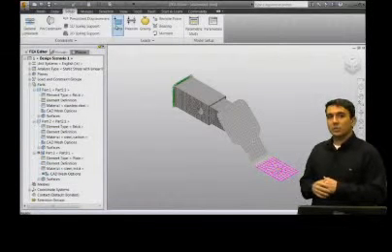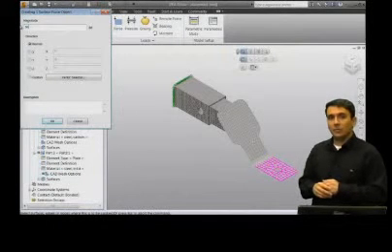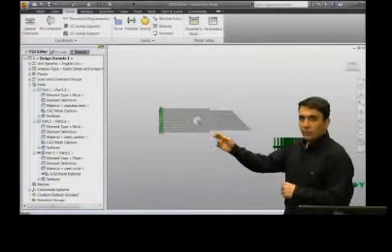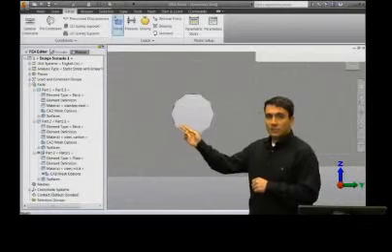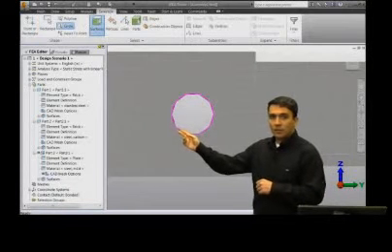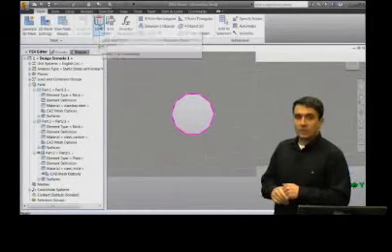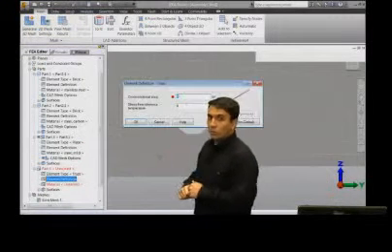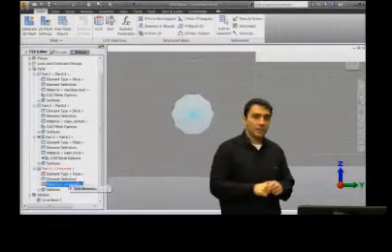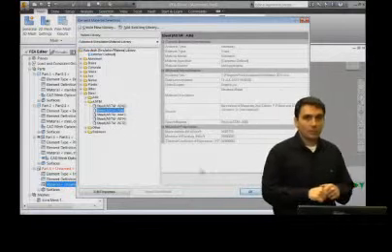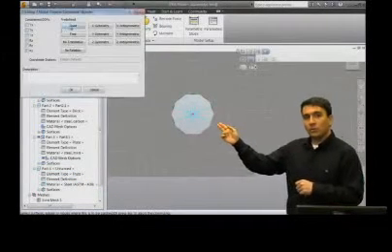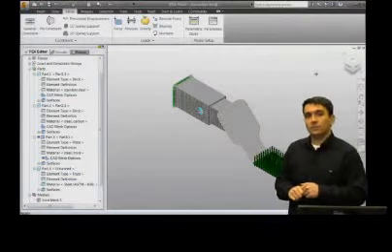So I add some loads and boundary conditions to finish the setup, and then I can run my analysis. But I also want to highlight this new functionality of nodal associativity, so I'll add a joint. I select the surfaces at that hole and create a joint. And you will notice that you can set your part, surface, and layer information for joints in this release as well. So I select the material and select the central node to assign a nodal constraint.